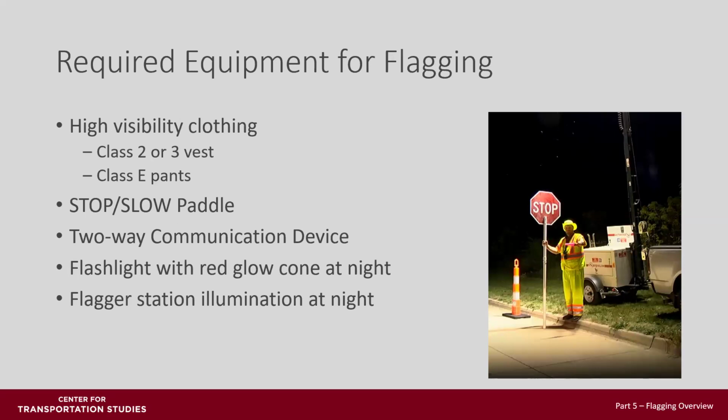Along with high visibility clothing, flagging requires a retroreflective stop-slow paddle, a two-way communication device such as two-way radios as described in the video, and for nighttime flagging, a flashlight with a red glow cone and an illuminated flagger station is required.